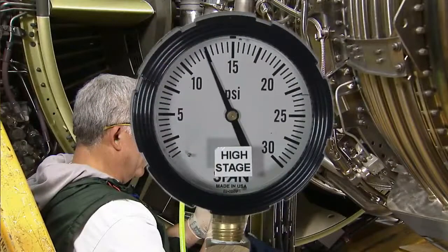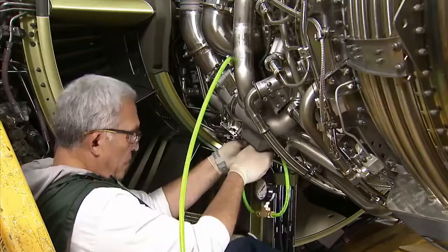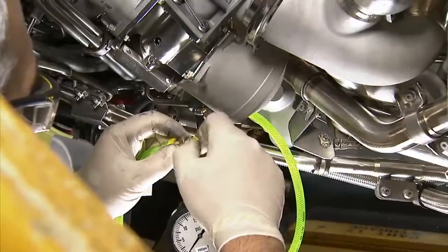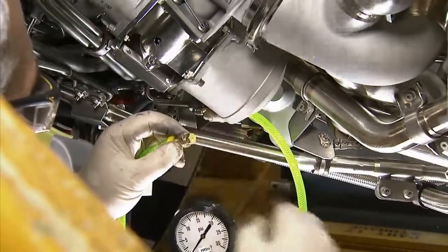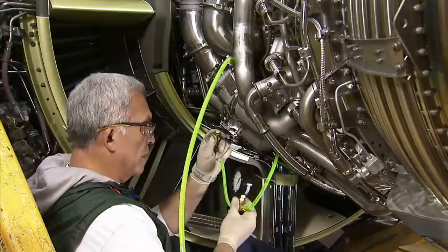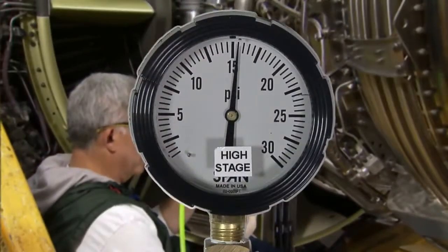If the pressure to the HSV is low, you will need to isolate the HSR and HSV to find the problem. Remove the test pressure line from the HSV, then install a test cap with a 32 thousandths of an inch hole in it on one end of the line. Note, this cap has a hole because the HSR needs a small amount of leakage in order to regulate the control pressure. The normal leakage in the HSV is usually enough for this. There are instructions in the AMM for making this cap. If the pressure is still low, the HSR is faulty, or there is a leak in the control sense line. And if the pressure is now correct, the fault is in the HSV.